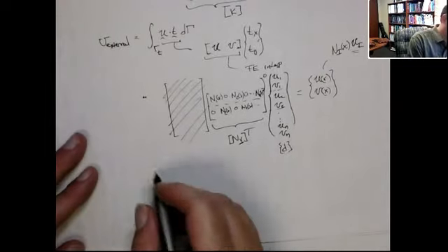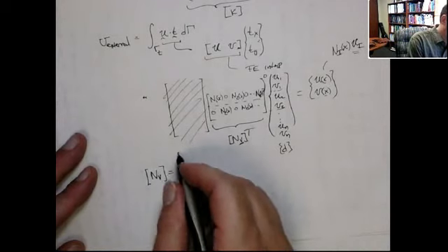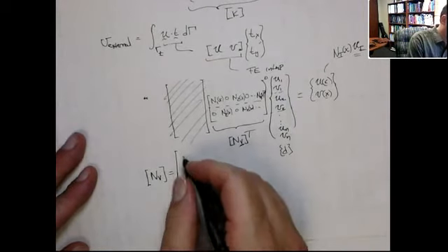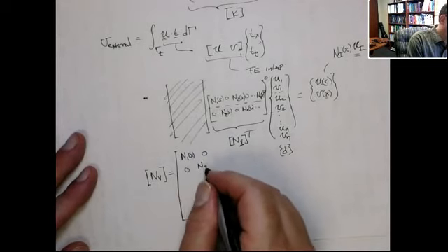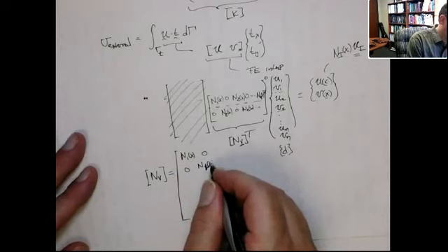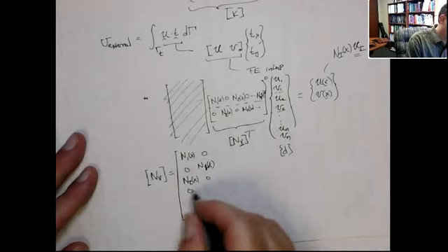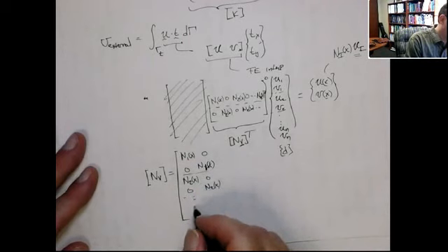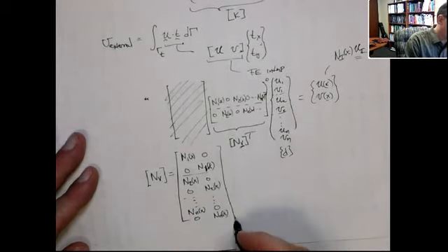So what I really mean by this is, let's do it this way. I'm saying that NV is written as follows. I'm going to write it a little more neatly. N1 of x, 0, 0, N1 of x. Okay, it's not that neat. N2 of x, 0, 0, N2 of x. So on and so forth until we get to N_n of x, 0, and then 0, and N_n of x, the last shape function. All right?